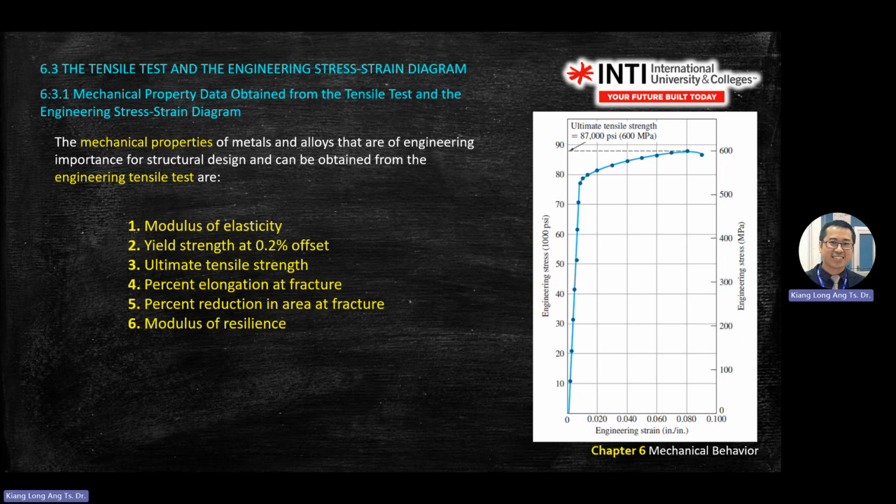Okay, let's say you get an experiment like that, right? You get an experiment value like that, and you want to estimate where the plastic starts to happen. You can use a ruler to join all the dots here, but this is not accurate. So we'll use a certain percentage. Some countries use 0.2%. Some countries use 0.1%.